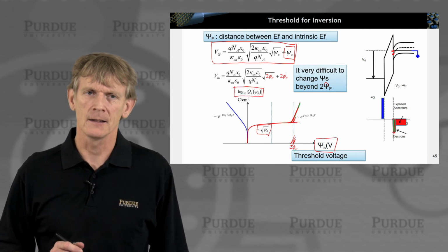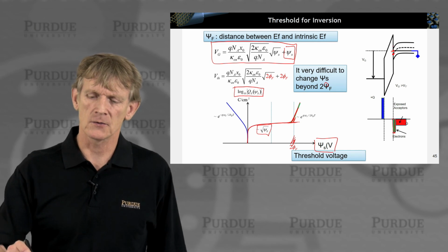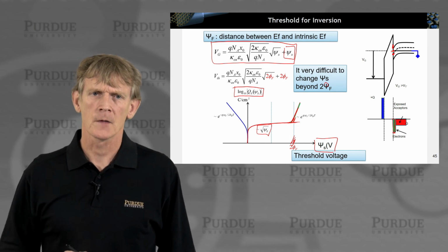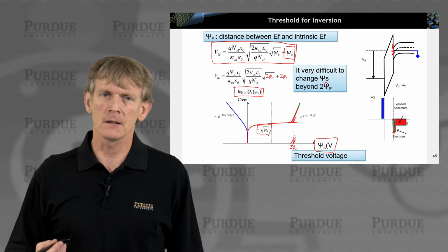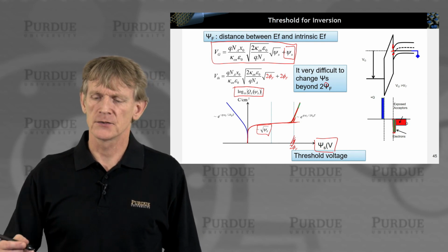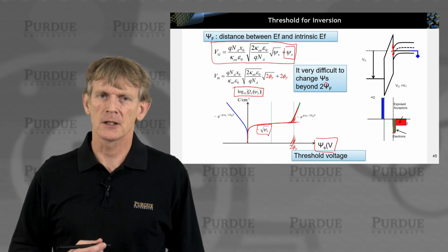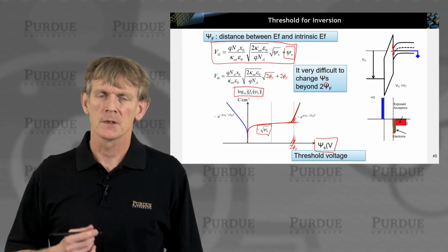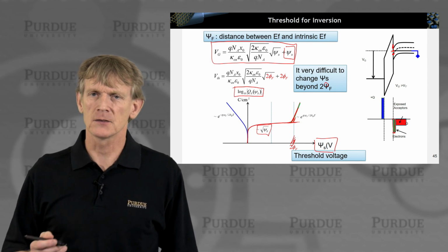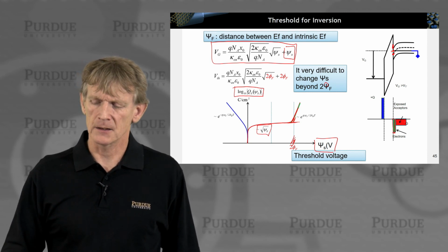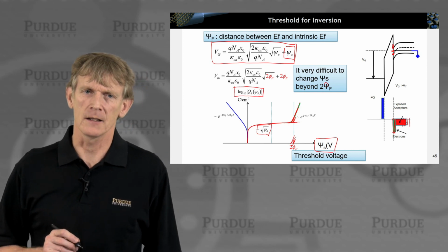And you can pile a lot of electrons into this triangular notch here with very little potential difference. So with very little surface potential difference, you can ramp up your occupation of states rather dramatically. This is different from extending out your depletion region as a function of psi s.